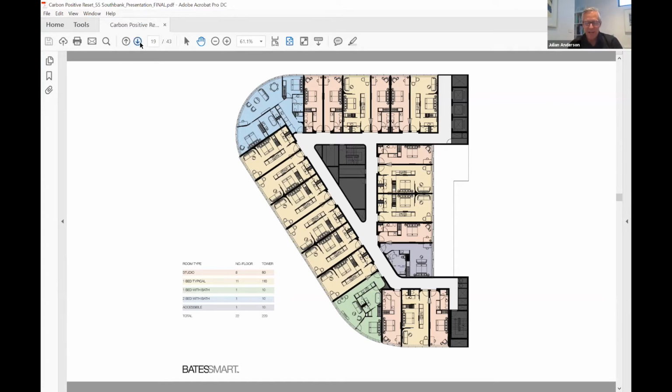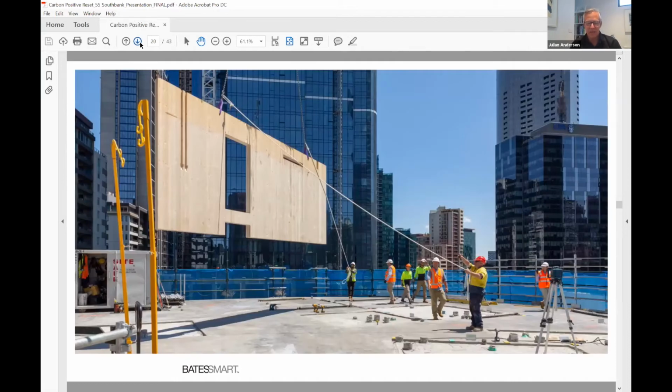So in terms of the cross-laminated timber, this is one of those panels that's gone into making up the interstitial walls. There was approximately 5,300 tonnes of cross-laminated timber used. And the CLT will offset about 4,200 tonnes of carbon dioxide from the atmosphere. And all of the timber sourced was supplied by suppliers with Forest Stewardship Council certification. Interestingly, I think the project, if it had been built using concrete precast panels, would have required 5 times the number of panels, and therefore 5 times the number of crane lifts.